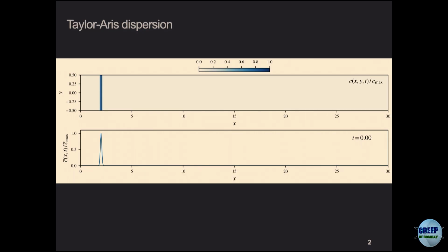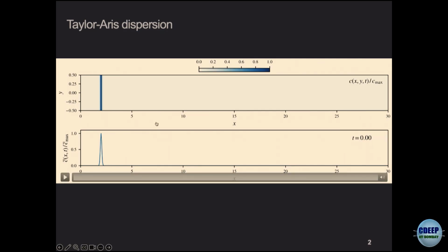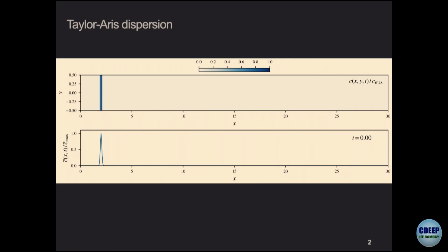Okay. Now what you'd expect to happen is, immediately the velocity profile should distort this slice, because the center of the slice will move faster than the stuff near the walls, which in principle should not move. Now, of course, this is some diffusing species, so there will be some diffusion, which will further distort the shape. And so we'll see how that evolves. Now, what is of interest is, if you want to know the details, you have to just solve the equation, as I have done here, and I will show you.